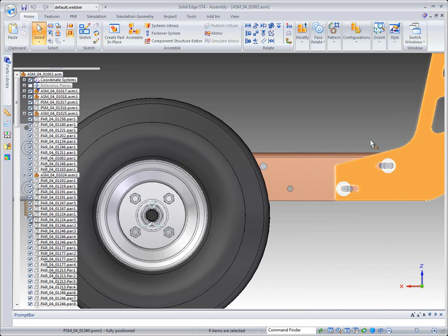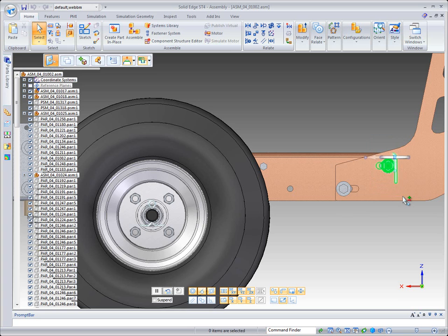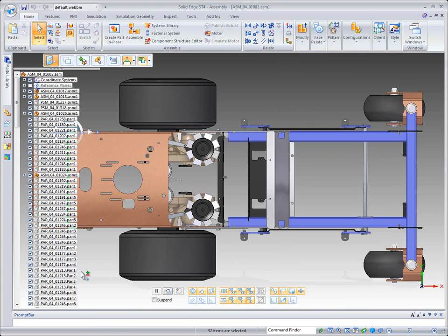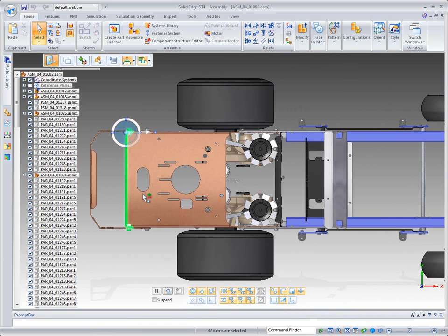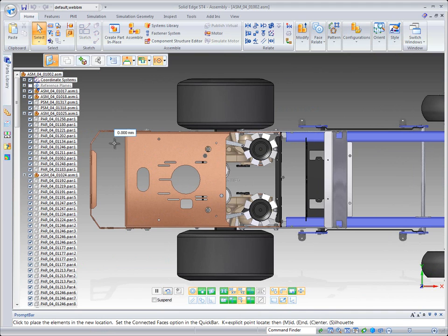And what normal to the screen will allow me to do is, as I window select an area that I want to make modifications to, that's actually picking those faces, those components, or those features in the Z depth of the screen. So here you'll notice we've got some different things selected, and we'll just go in and stretch this back area about 50 millimeters.